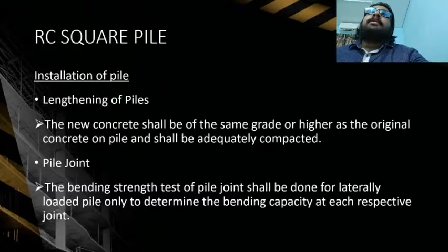Next, the lengthening of piles. The new concrete should be of the same grade or higher as the original concrete on the pile and should be adequately compacted. Next, the pile joint.